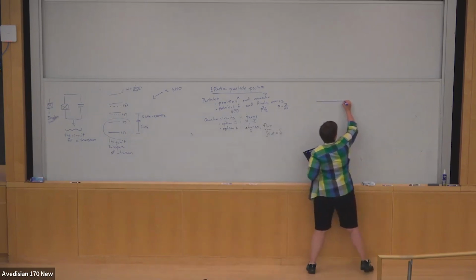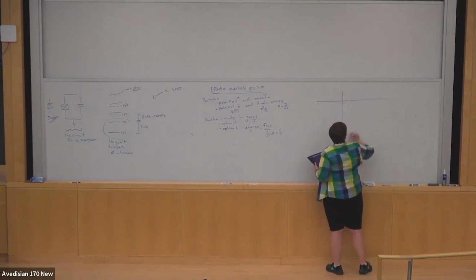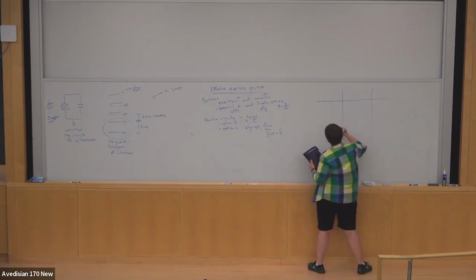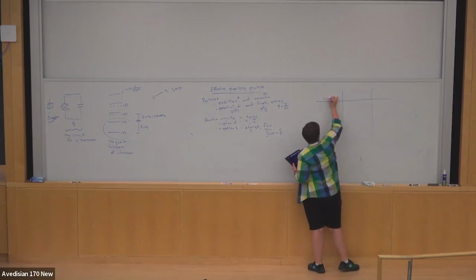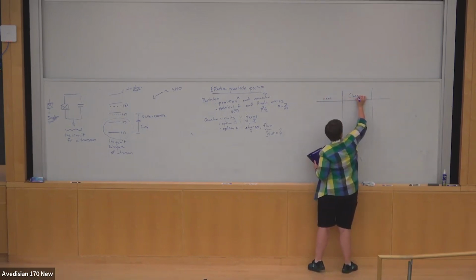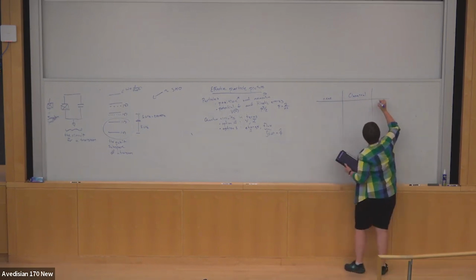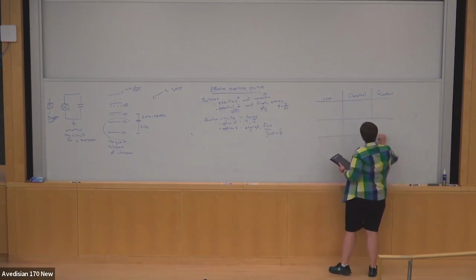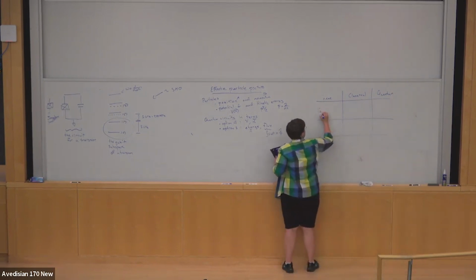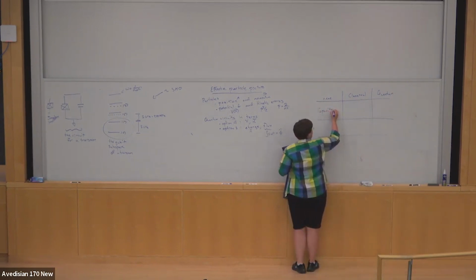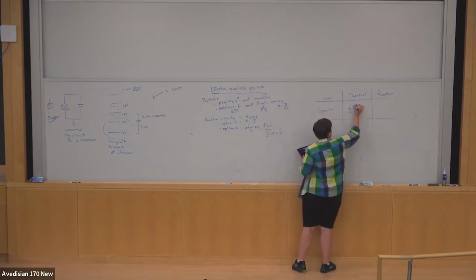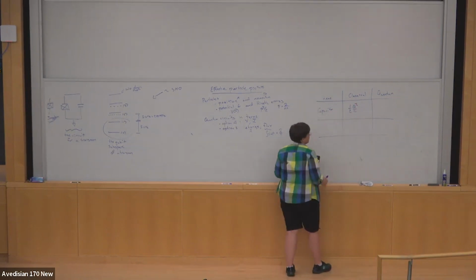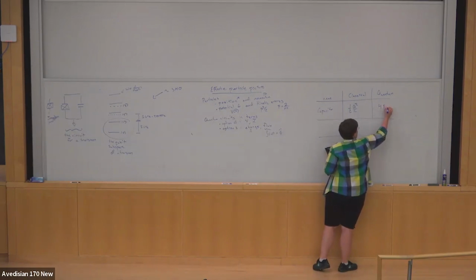And so now we can go back and look again at the different circuit elements, and we can look classically and quantum and make an energy lookup table. And so for the capacitor, the energy stored in the capacitor is 1/2 q squared over C. And so that's going to be written as 4 EC n hat squared.